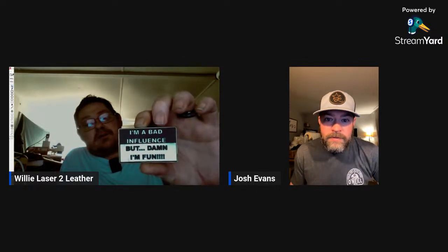Yeah. So this is some of your acrylic with the UV. Now, I like it. The UV has a little bit of a trick to it. For whatever reason, the bandwidth or the length of the light waves, unlike a CO2 where it's going to hit the top of your acrylic all the time, even if you've got it focused out or in, it will actually go into the material, any clear material. So you can engrave on top, you can engrave inside, and on glass and stuff, you can actually engrave on the back side of the glass. Oh, wow. Just by adjusting the focus on the UV.